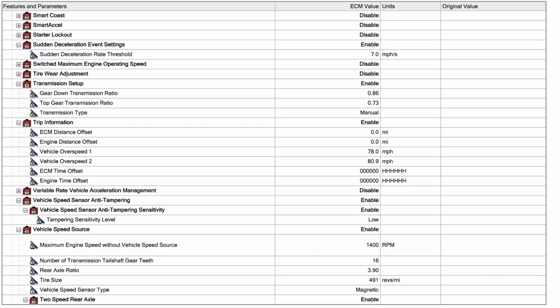If you turn that sensitivity level to high, I think it just cuts the amount of time down that it looks at before it trips the fault. When you set it to low, it allows more time. I never saw a problem with that in the last 10 years I worked with that fleet, but it's just what I did. If I bought my own truck, I would turn that whole feature off, because if there was ever a time where there was a problem and the vehicle speed sensor failed, if you unplug it and that's turned off, you should be able to drive as fast as you need to drive down the highway.